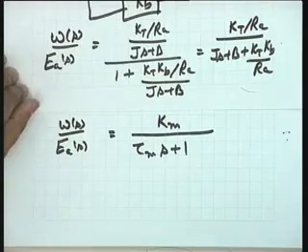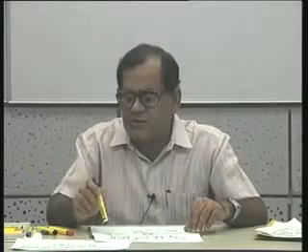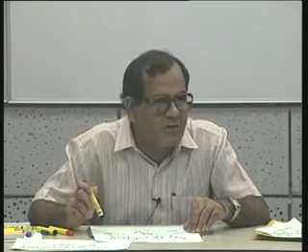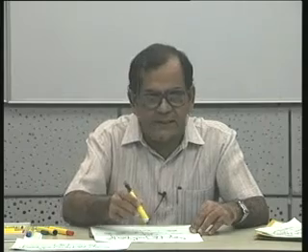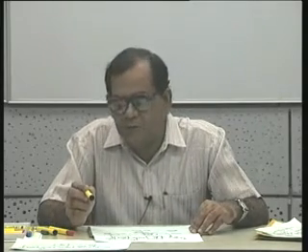Equivalently, in the time constant form, what happens to the time constant because of Kb? Does it increase or decrease? The time constant because of Kb decreases, and as you know, smaller the time constant, faster is the response. So, quick damping means the oscillations are damped out quickly and the motor comes to the steady value quickly, and this is the characteristic of this inherent loop which is there in an armature controlled motor. I hope this is okay.